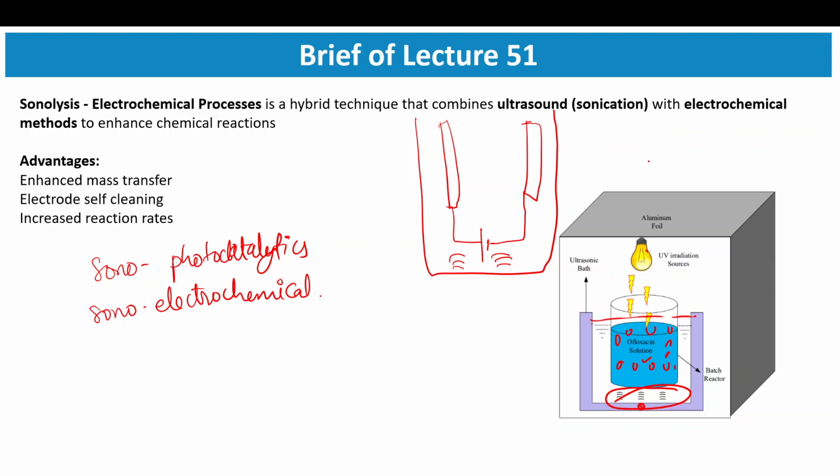The bubble bursting will enhance mass transfer and reaction rates, and also it will increase the self cleaning of the electrode. It will ensure that electrodes are clean, and the deposition of some byproducts it will also reduce, right? So that is the advantage of combining ultrasound or sonolysis with the electrochemical process.